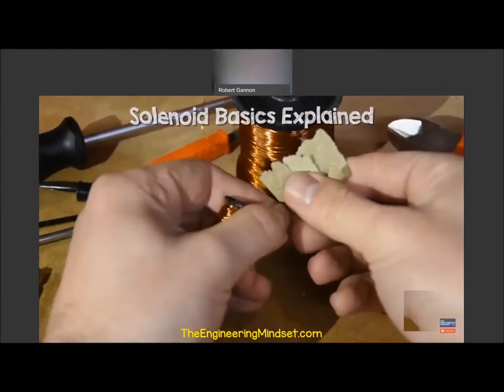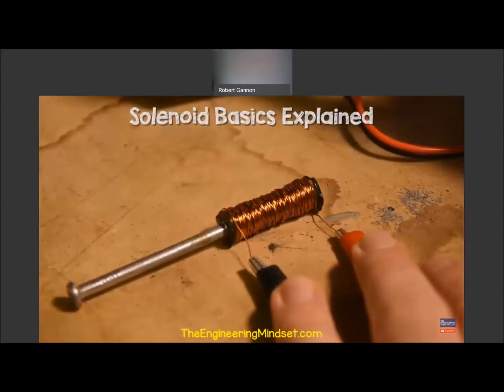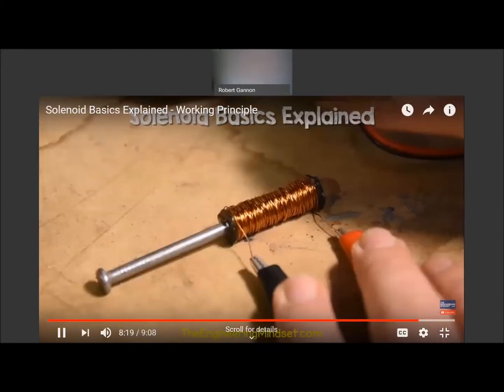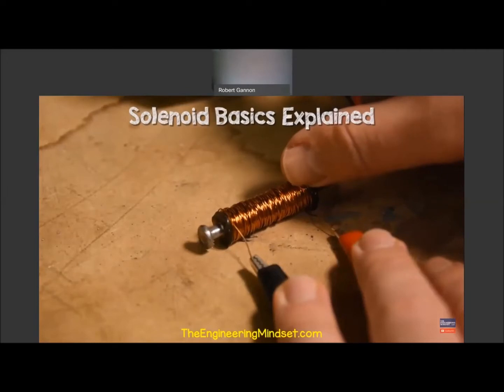And we want to just use some sandpaper to remove the enamel, which will give us a better electrical connection. So if I place my iron nail concentrically within the coil, but not fully within, you see that the nail piston is pulled inwards by the electromagnetic field as current passes through it. If we were to place a spring at the end, it would return to the original position.